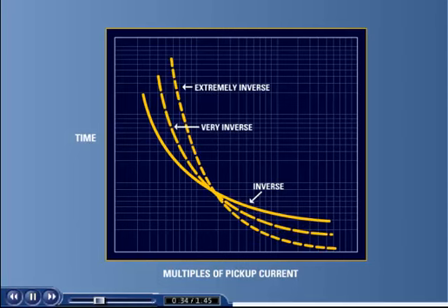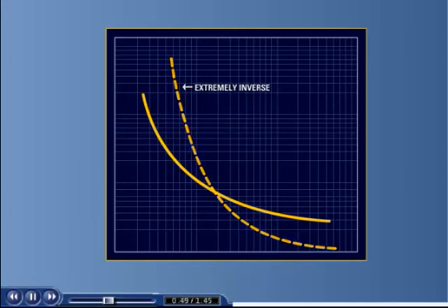They are said to be a family of curves. In other parts of the world, different sets of curves are used, and some, like the Multilin relays, allow you to create your own curves. During the selection of the curve, the protection engineer will be able to use a time multiplier to effectively shift the curve up or down on the time axis, in addition to a scaling adjustment to normalize the curve to the desired pickup level. That is to say that the pickup will be equivalent to 1 per unit or 100% on the x-axis.